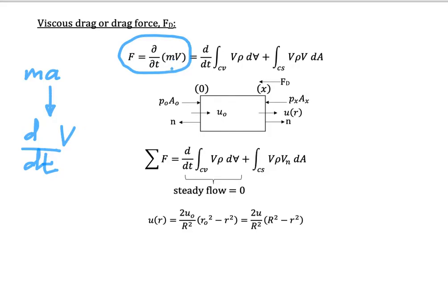And then these forces actually come from the control volume and also from the surface. So here, these are the common terms for the Reynolds transport theorem. So we need to write it as this one. We write d/dt of the integral over the control volume of v rho dV, where dV here is the volume, and the integral over the control surface of v rho vn dA. Okay, and then here I will add, so this must be vn.